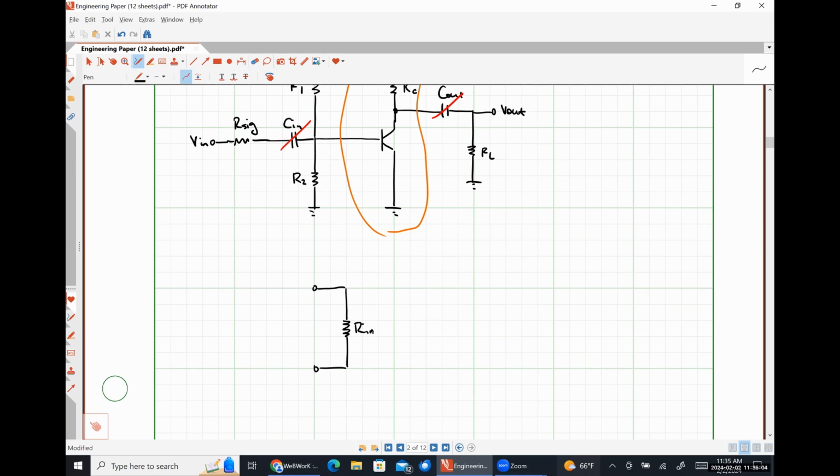this guy right here, this resistor, represents the input resistance of my amplifier circuit that we just looked at. I'm going to call this R in prime. Okay, we're going to wind up finding an input resistance for our new system in terms of how it's connected to our old system. Okay. Over here, I have A V times V in.